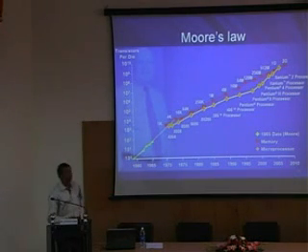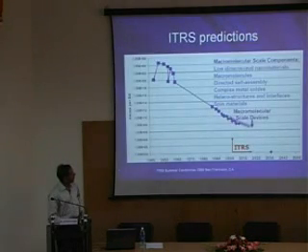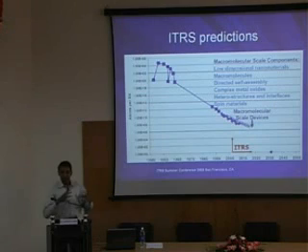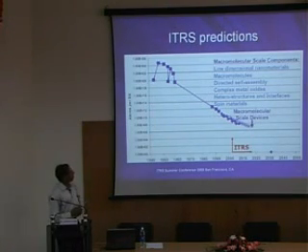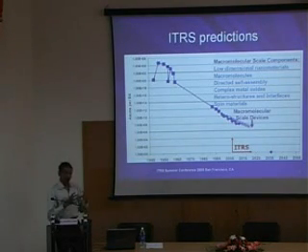And this is the very well-known Moore's law, which tells us that the complexity of these devices is doubling approximately every 18 months or so. Now, while the complexity of the integrated circuits is increasing, here I have shown another picture. This is a prediction from ITRS. The number of atoms that you use per bit has drastically come down.